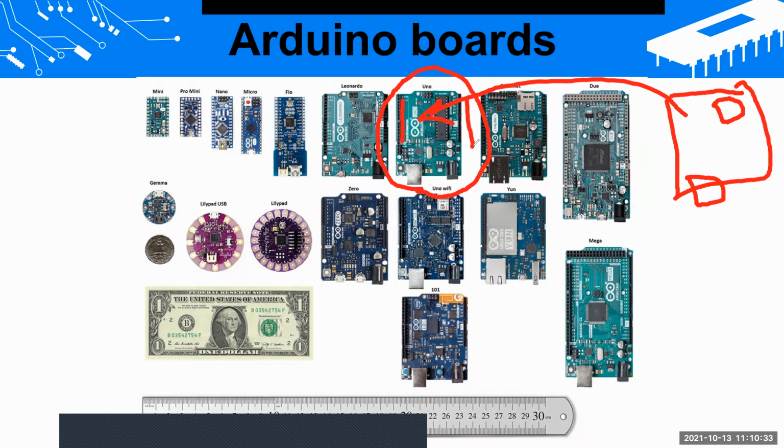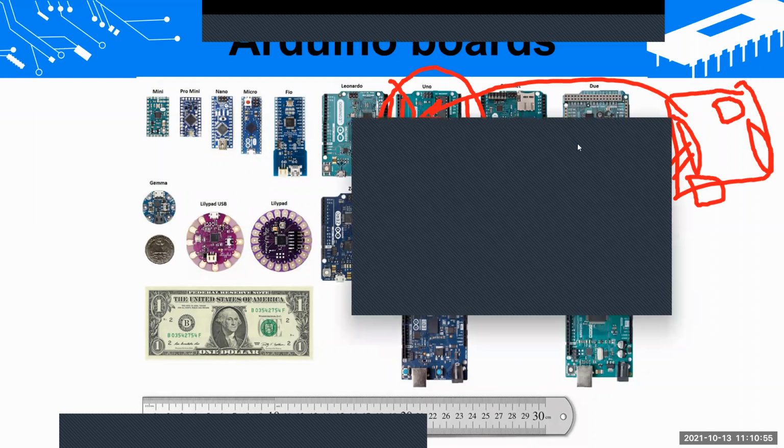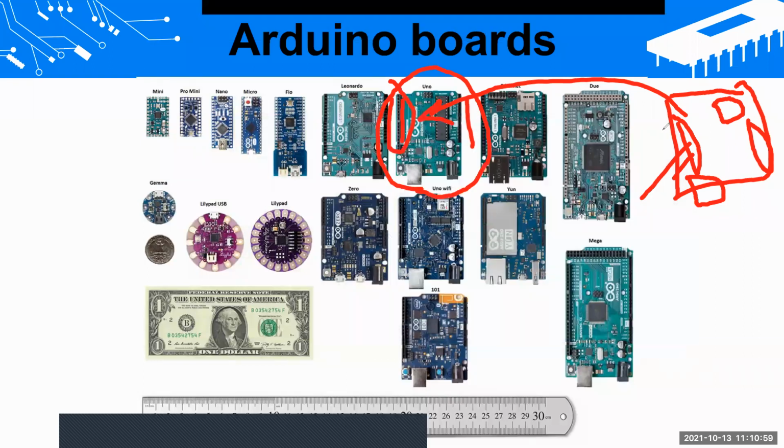Then it will again map these pins to another layer, so these pins are not wasted. The Ethernet shield only requires a certain number of pins, so it will take those, and the rest of the pins we can use from the top of that shield. Yes, we can put certain shields on top of each other. We can connect a set of shields.